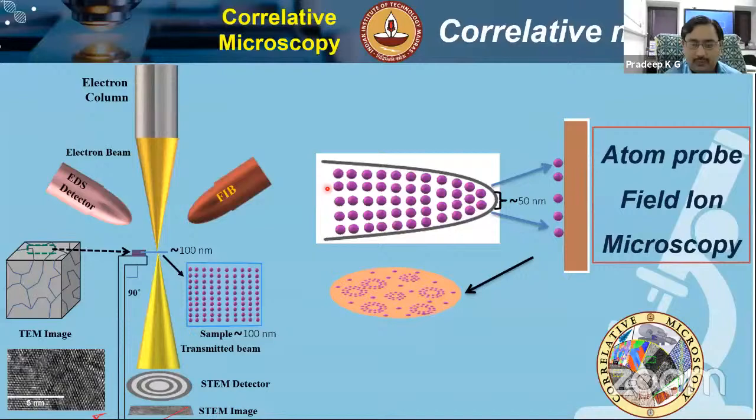Yeah, good. So what you see here, this schematic nicely explains that when we have these materials or atomic arrangement in materials being looked at with an electron beam, we get a projected view. But the same sample, or a different geometry of the same thickness, can be produced in this order. That means you have this periodic arrangement of atoms in most crystalline materials being arranged in this form. But if we now do atom probe tomography, we are evaporating atoms one after the other. That means it's a destructive process. We are losing material layer by layer as and when the process of field evaporation continues.